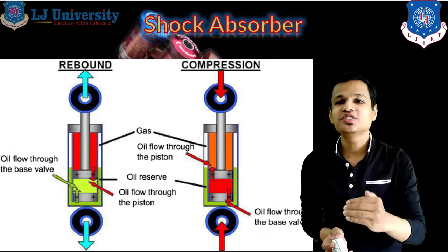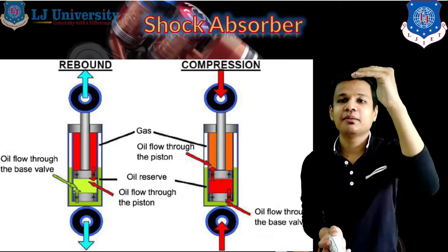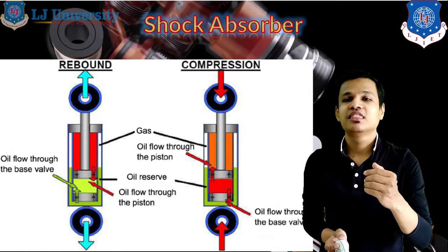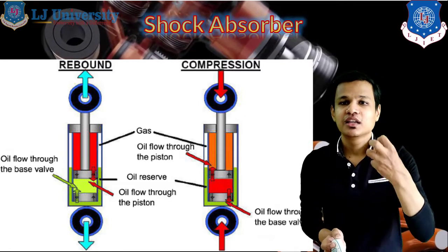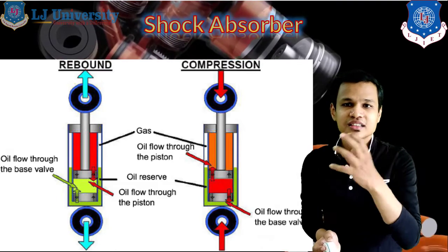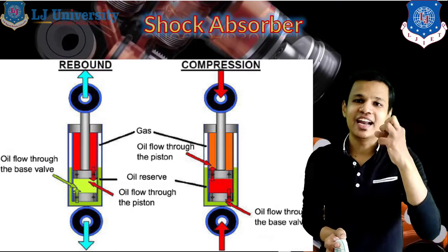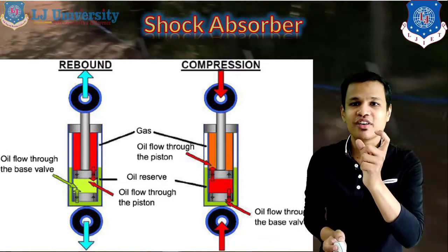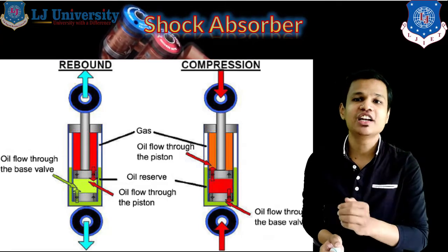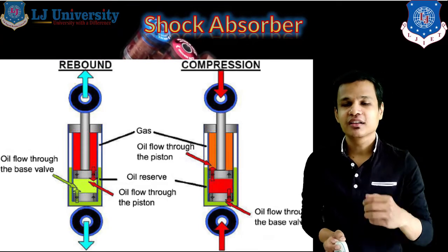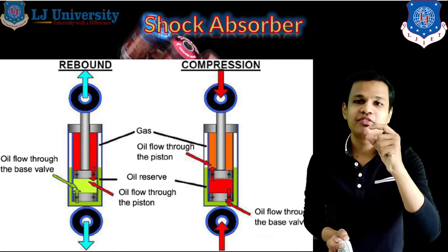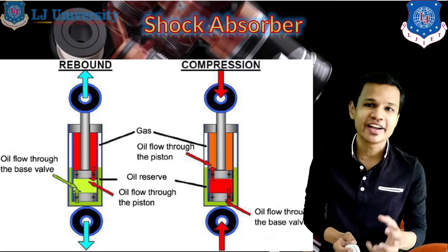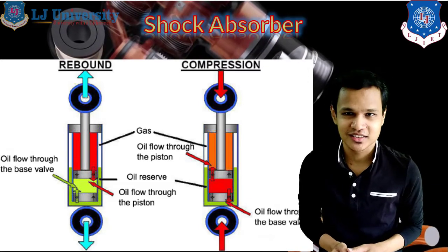This procedure will continue for some time, and because of this procedure heat will be generated in the oil. That heat will continuously be released to the atmosphere, and after some time the vibration will be absorbed. Sometime, which means a very small time, right? So the driver will not feel those vibrations, and if he does feel the vibration, it will be for a very small time. So this is how comfort is provided with the help of the shock absorbers.